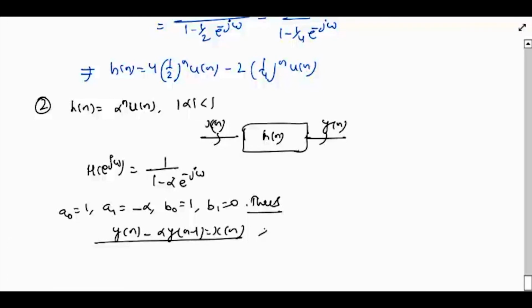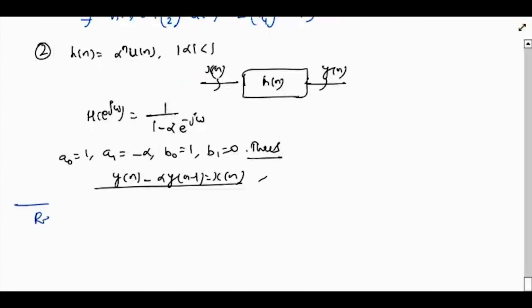Now let us take a step back, as we did in the case of the continuous time case, and see what are the conditions under which the infinite sum defining the discrete time Fourier transform is well defined. Okay. So let us recall that the discrete time Fourier transform of a signal x[n] is given by summation k equals minus infinity to infinity of x[k] e raised to minus j omega k. Now we are asking the question, is it that the infinite sum on the right hand side is always defined? What are the conditions that we can put on x[n] to ensure that this sum is always defined?